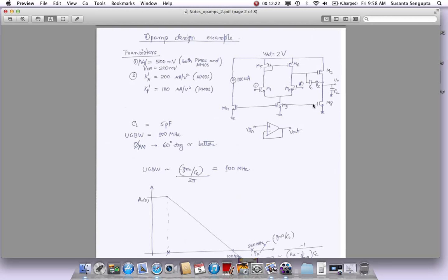The purpose of this test is to actually come up with a first cut hand design. Something that you calculate on paper, with pencil and paper, and you draw the circuitry, you come up with W over L values, you come up with things before you go to the simulator. Okay, do not go to the simulator quickly. That's what a lot of folks I've seen do. Do not do that. Try to at least come up with a first cut design like this on paper, which is what this is, and then go to the simulator for fine-tuning it.